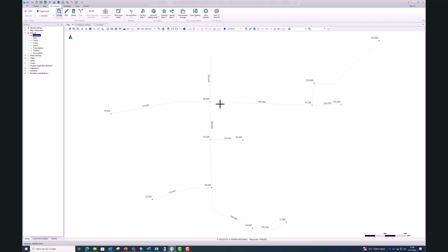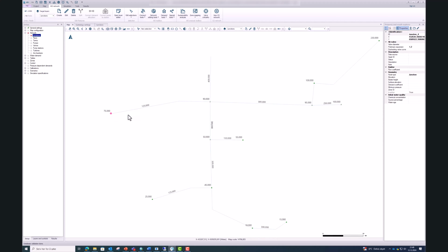So I see that I have my elevations here. So the way I do it manually when I put the elevation information in the manholes is that I use this identify tool, which we will be using a lot in this course. So just remember where it is. It's this circle with an eye inside of it. So with this highlighted, we can click on our drawn junctions. This is from the layer that we imported, so it's not a model element, but the junction is a model element.